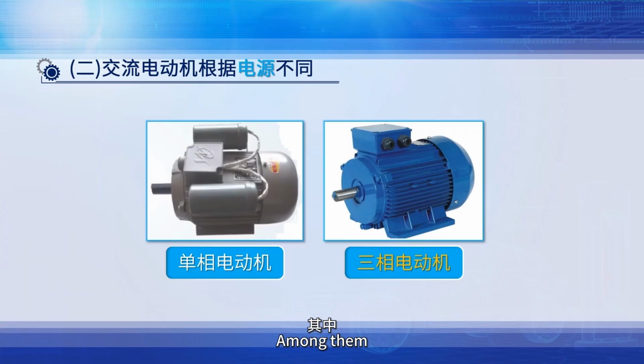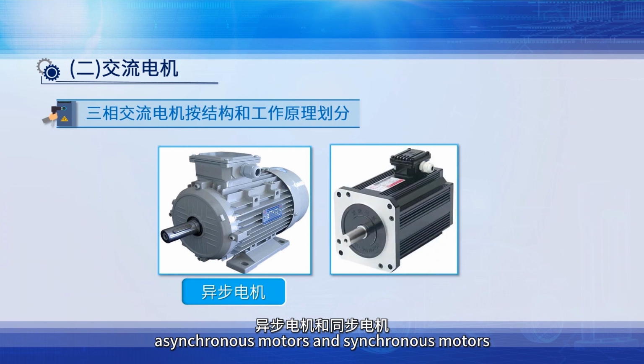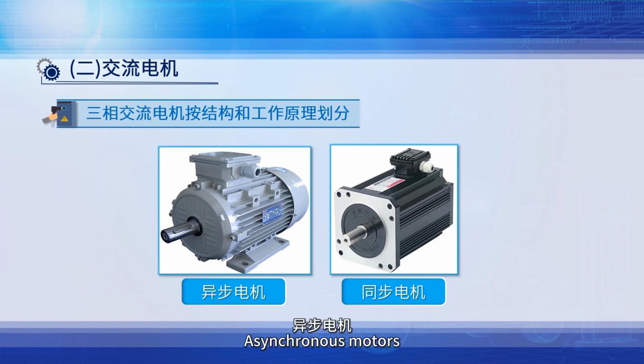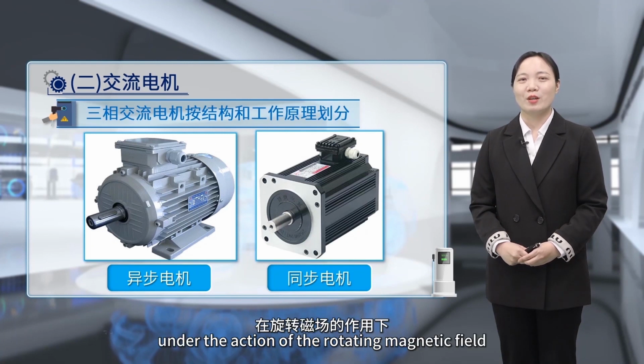AC motors can be divided into single-phase motors and three-phase motors according to the type of power supply. Among them, three-phase motors are commonly used in new energy vehicles. AC motors can be further divided into asynchronous motors and synchronous motors according to their structure and operation principles. Asynchronous motors, also known as induction motors, have their rotor placed in a rotating magnetic field and obtain a rotating torque under the action of the rotating magnetic field.